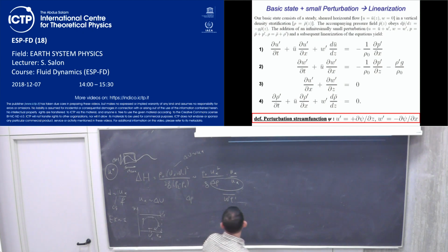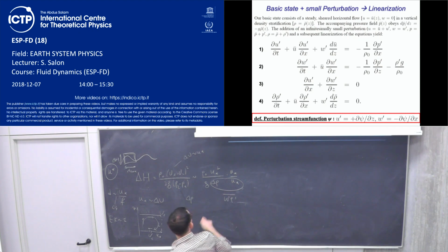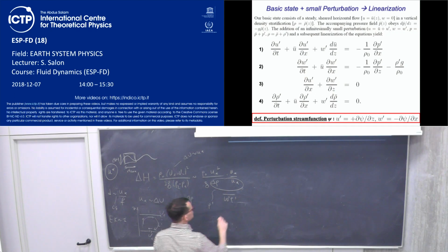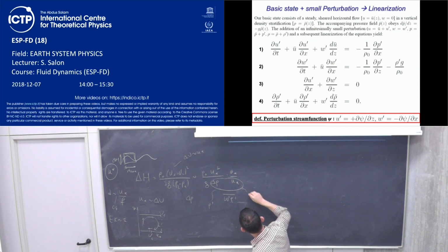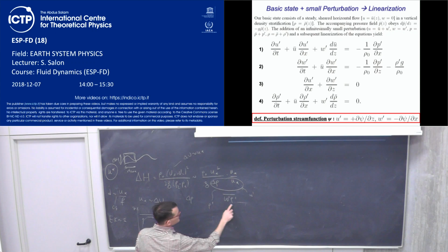So what Cushman says is, let's consider this term here as a vertical turbulent transport of density perturbation. Okay? So delta rho can be in some sense represented as a density perturbation. U star can be represented as the perturbation of the vertical velocity. And what we obtain is a turbulent measure.